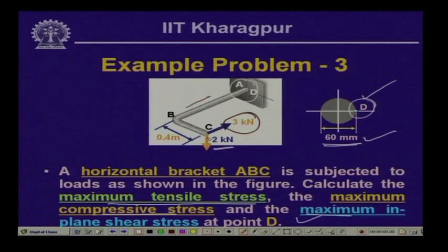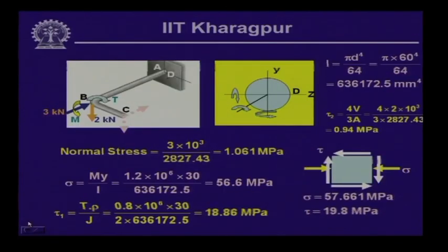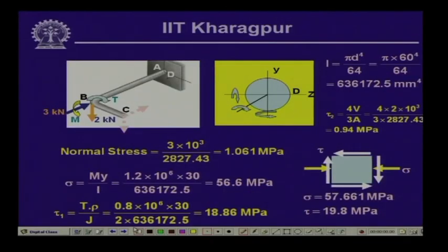Now, as you can visualize, if we transfer these forces acting at the tip to point B, they will be associated with some moments. Let us analyze the forces first, to see how we transfer these forces to the tip of this beam. This bracket ABC we can reduce to a cantilever beam AB, which is fixed at A and free at B, and in the process we can shift this end loading to point B, which is the tip of this cantilever part.